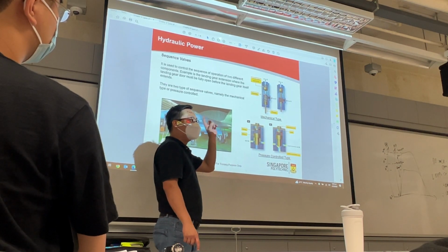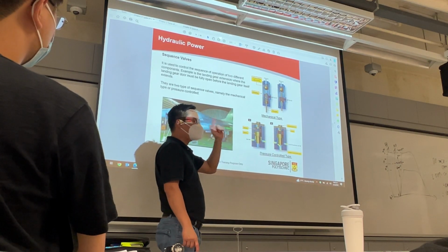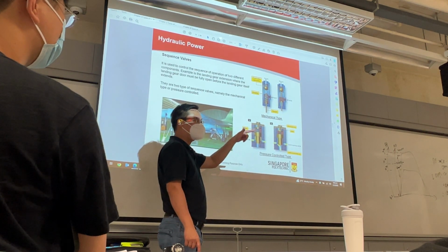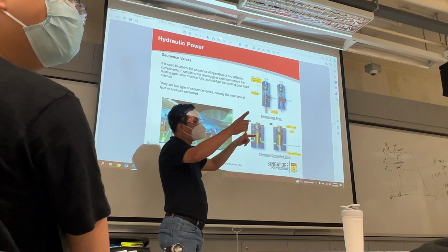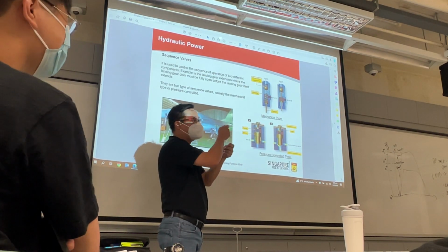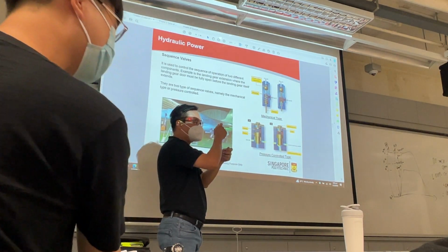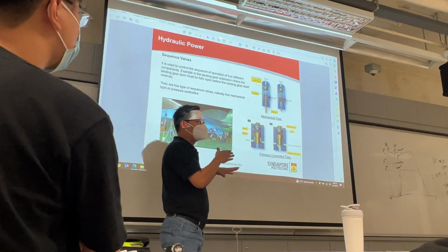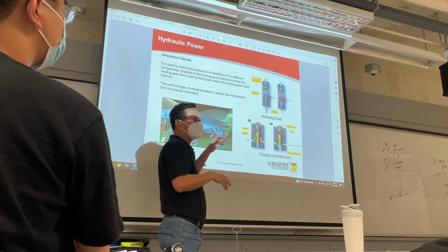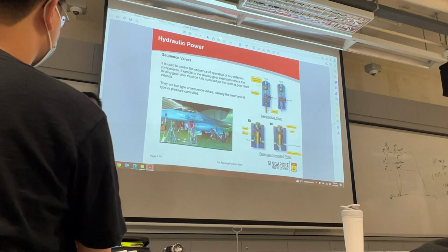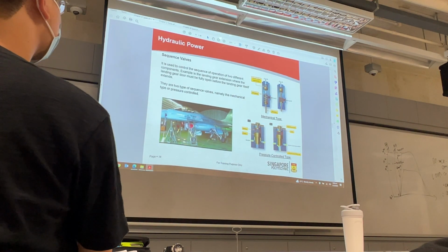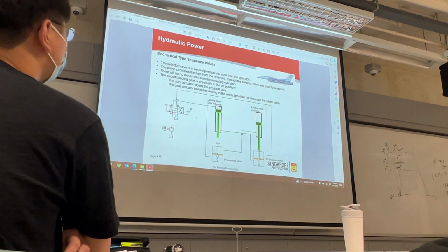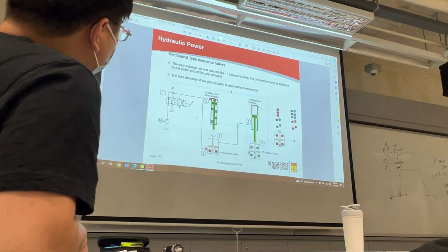Today you go home, nobody at home, the door is closed, the gate is locked. Just go in? You can't, you must open the gate, there's a sequence for you. Open the gate before you open the door. Same thing. If the gear and the door close at the same time, move at the same time, the door was damaged. But usually sequence valves are quite reliable. So over here, the next few slides is just for you to appreciate how the sequence valve works. Okay, appreciate.